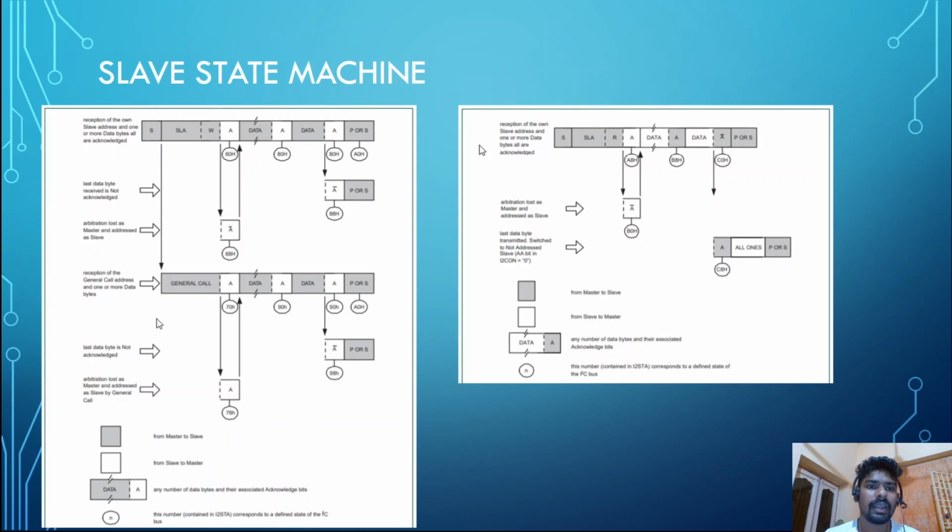If you are implementing a slave, then the following states will occur. One has to implement the state where the slave responds with ACK or NACK for the slave address, one has to implement the data byte acknowledgement, and one has to implement the general call address.